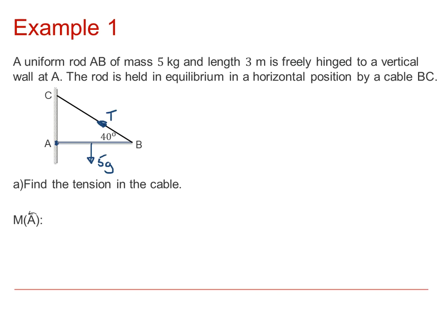Now there are other forces acting. Those are forces which are acting at the hinge here. We don't necessarily know which direction those are going to act in, so one way of considering this is to split those into two forces, X and Y, which in some questions we may need to find. But for this question we're asked to find the tension, so an obvious choice of point is A to take moments about.